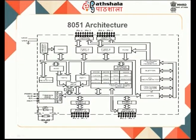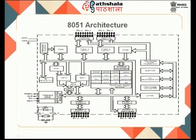This is used for holding the address of the next instruction, where we have a PC incrementer. Each time I get an address, I go and fetch the data, and it comes here as data or instruction, and this comes to my instruction register. From the instruction register, the instruction is decoded, and the timing and control unit sends control signals to all the parts of this architecture.